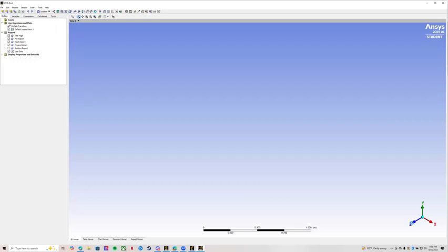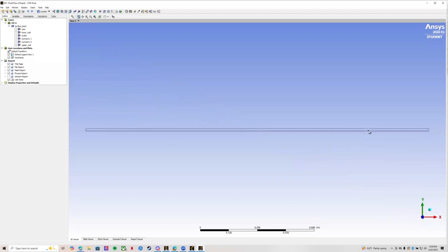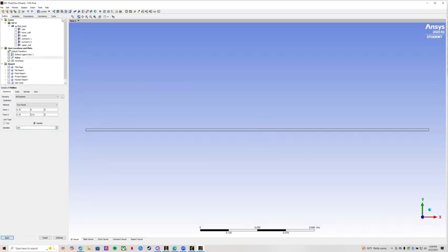And here's where we're going to put the contours, the vectors, and our velocity profile. So first thing we're going to do is pull up this 2D view. We're going to want to put in a location, go up here, pick lines. So we need our midline, where that's going to be our middle point. In this case, it's going to be 0.750 because we have a 1500 long thing. Make sure you make it the height of your pipe. So in our case, since it was 10 millimeters, it needs to be that. We're going to do 100 samples. And once you press apply down here, you should see that yellow line appear.